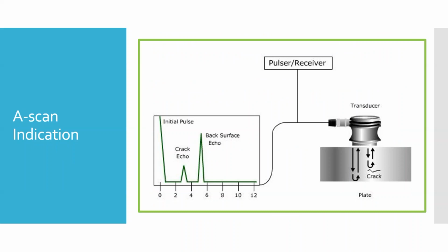And then you can use that to calibrate your speed of sound. You say, I know how thick this piece of material is. I set my initial pulse at 0, and I adjust my tester until, say, my back wall is about 4.5 inches thick. We'll say 4.5 inches, okay? 4.5 centimeters, I don't know, 4.5 units, whatever it is. And so you can use that to calibrate your probe.